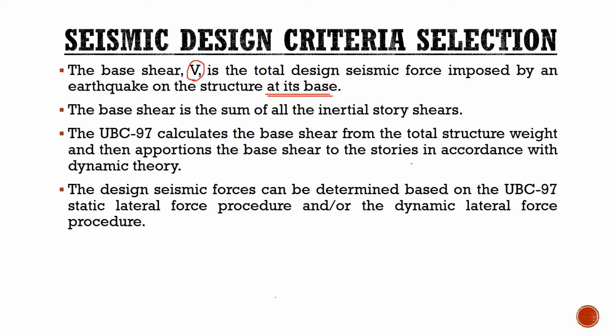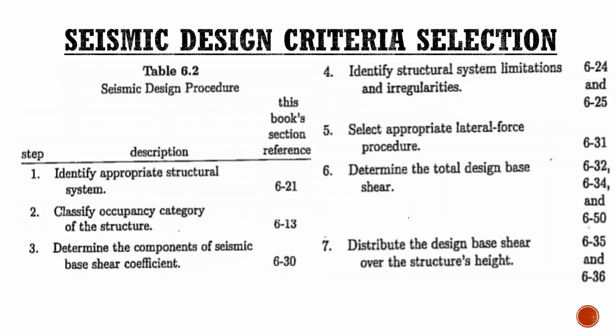So we will solve that later, guys, the base shear and then its distribution to every story. So the design seismic forces can be determined based on the UBC 97 static lateral force procedure and or the dynamic lateral force procedure. This is a bit complicated once you have dynamic. So more on static, which is the easier one for us, guys. The static lateral force procedure.